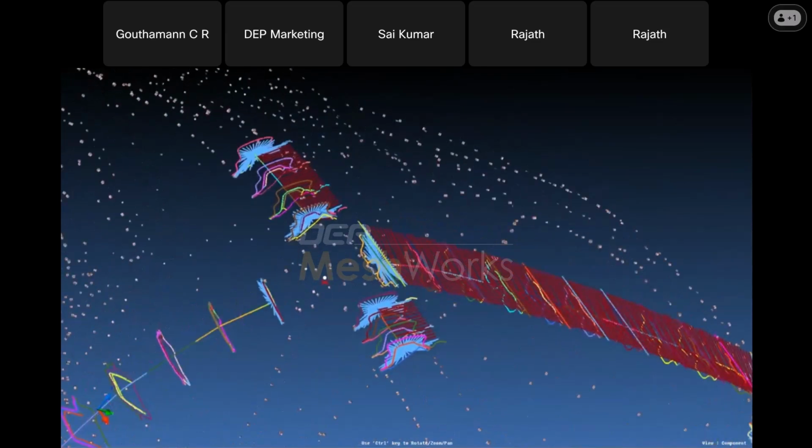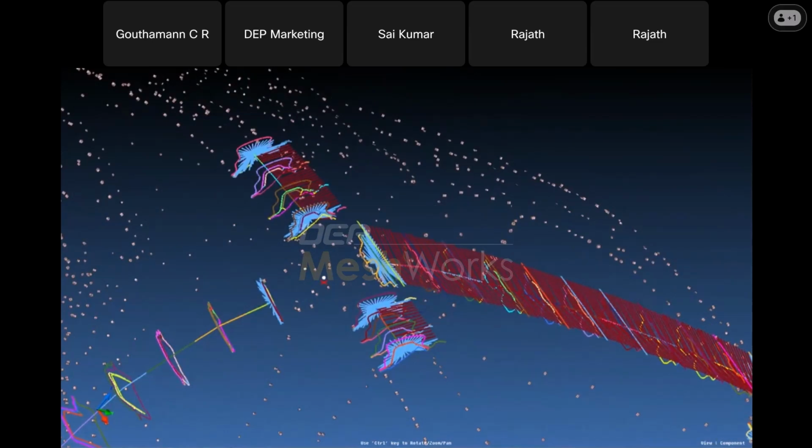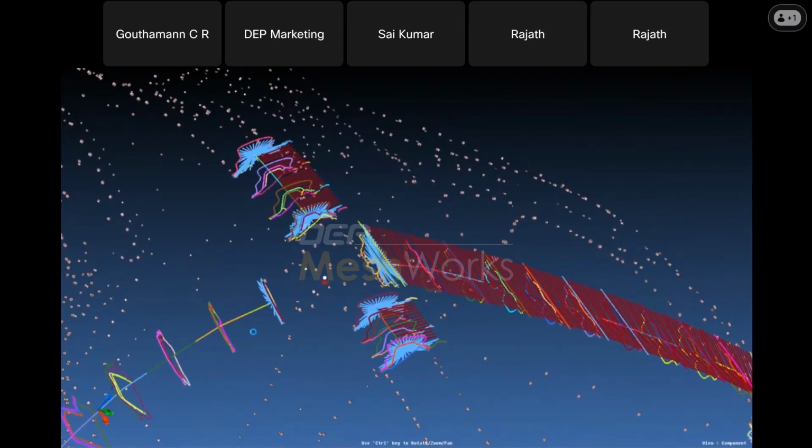And then we can specify the element size for the 1Ds and say create beam joint. So just by giving the rigids as the input and the center node as the input, we can create a beam joint using this tool. This would take about half a minute to a minute for execution.